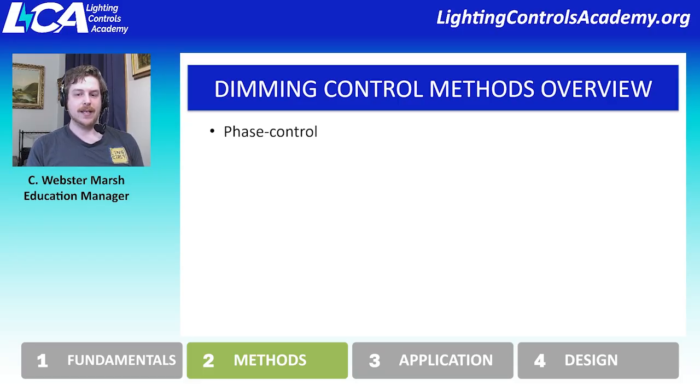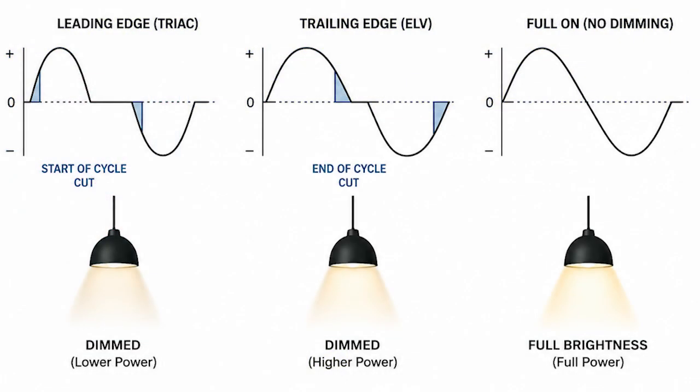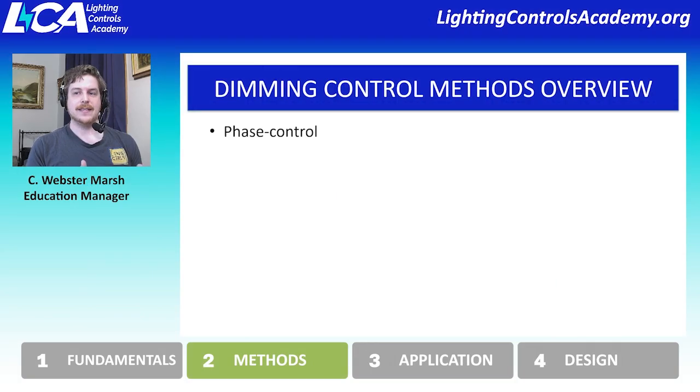Because of this, because we're affecting the power to the driver to communicate, low-end dimming on an LED tends to be quite erratic, because at that point we're choking the intelligence of its power source. And so that's why we typically have a lot of controlling for low end of the curve in phase control dimming, because of the fact that it is really unpredictable and can sometimes be really unattractive if we're not careful.